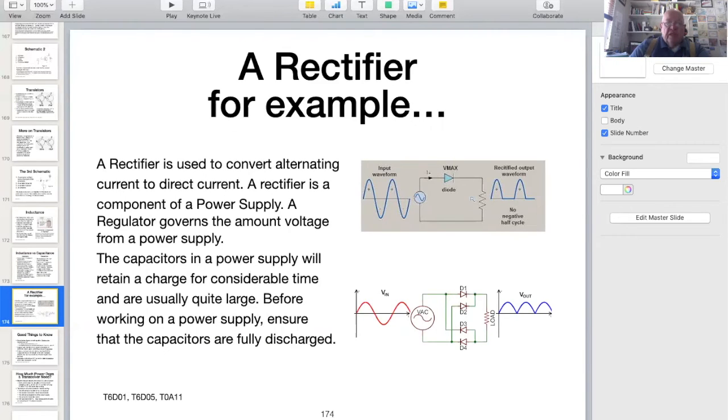As I said, diodes are very useful devices, particularly for power supplies. A diode only lets current flow in one direction. In the top right diagram, alternating current is being fed into the circuit. The diode only allows the positive side of the circuit to pass and blocks the negative side. The resulting output is a series of pulsed direct current.